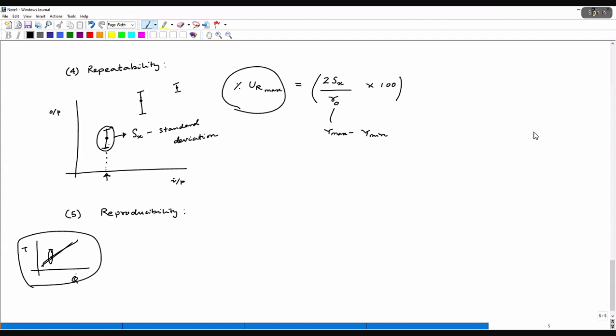Okay. Sir, I have a question here. Yeah. I agree with you on the repeatability, like, okay, if the same person measures the value and he gets two different values, that is the check for the repeatability. Yeah. And the reproducibility is if two different persons do the measurement, or at different conditions, that we can call it a reproducibility. Yeah. But one point I want to get clarified is, the person needs to use the same instrument, right? Like he cannot use a different instrument, right?